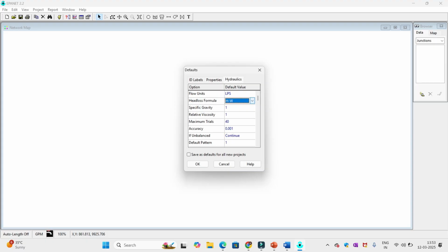It is mostly useful in long pipes where you are simulating a very lengthy piping system. And also this is valid only for turbulent flow. This formula doesn't give you good estimates in laminar flow. So generally Hazen-Williams is used to just take a ballpark number. This may not give you an exact calculation.